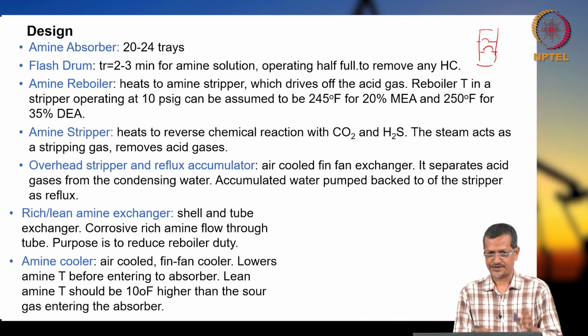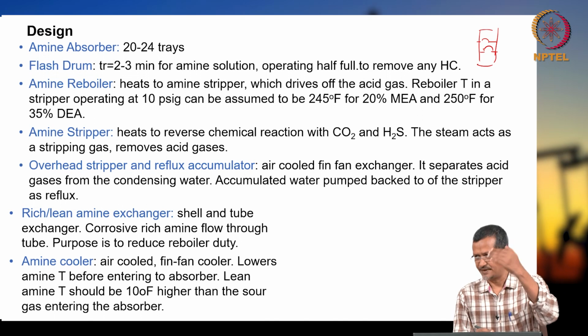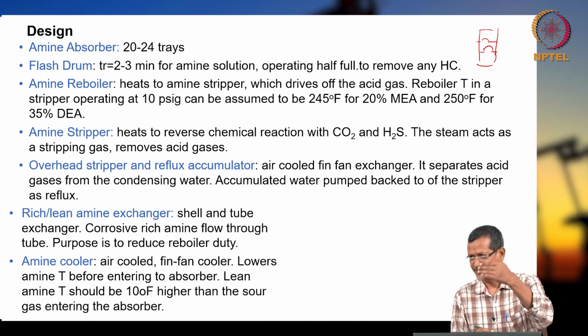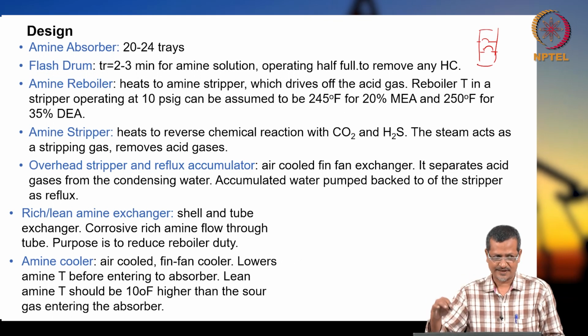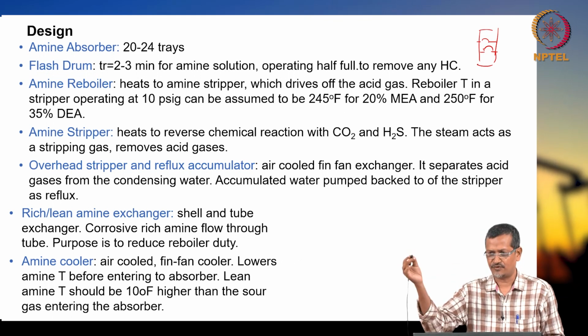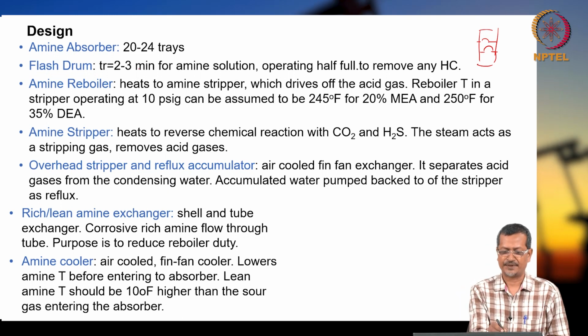So in the tray, the amine solution will be there. When it is bubbling up from the bottom, it will be mixed up. When mixing is happening, it will release all this H2S, and pure sweet gas will go out from your system. Flash drum retention time is around 2-3 minutes.